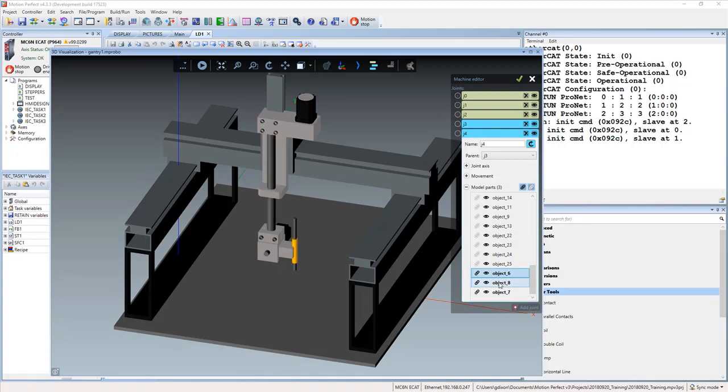And what you sometimes find, we looked at a model that someone had done at one point. So you see, sometimes you get models where every single nut and bolt is a separate item, and then you have to group them together and animate that as a group. If it consists of a lot of separate parts, it can slow down the animation. So you've got to be a bit careful of that.